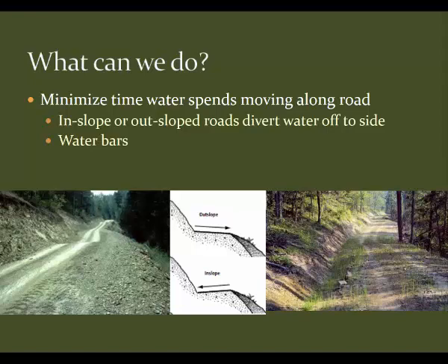So that involves more expensive construction. It involves us maintaining culverts, making sure they're cleaned out so they don't get clogged up. But these insloped roads are a little bit safer for people to drive on. And so that's one of the motivations that we might use to create insloped roads in more high traffic areas.